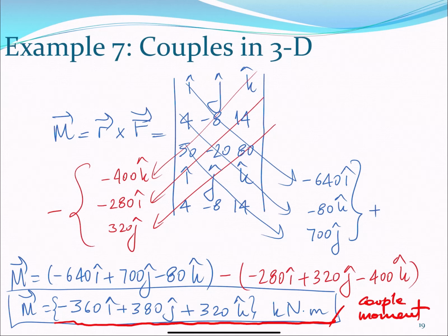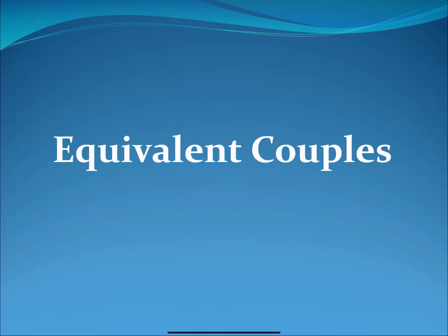That is the couple moment we got. And then you could try to verify this by calculating the moment of one of the forces about the origin, calculate the moment of the other force about the origin. You add them together, you should obtain this value. So this is the end of the couple moment.